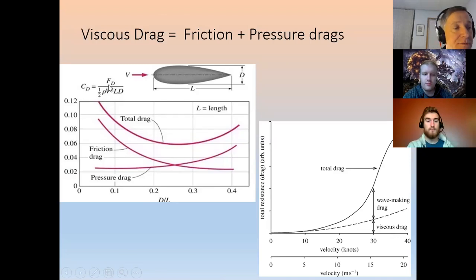So if you're solving for F sub V, the force caused by drag, it's the drag coefficient times the velocity squared times rho L D and all that. And I've got in the book some coefficients of drag in there. So it's based on shape, and you're experts in shape. So if you're trying to reduce drag, you want a low drag coefficient and you want a low velocity. That's always good, I'll say.